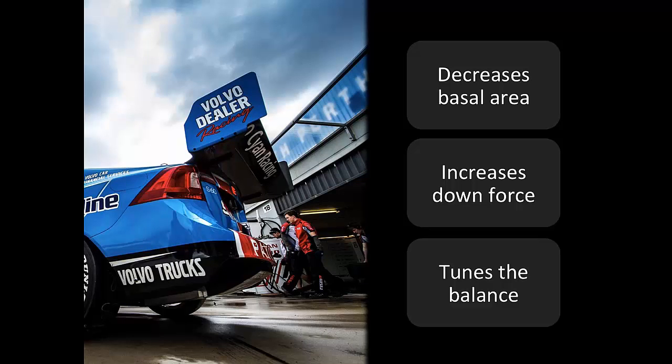So the diffuser can help with increasing downforce, basically by acting as a venturi for helping the exiting flow on the car. One thing you'll see when we developed the Volvo, I did want to put strakes and things on there to increase its efficiency, but I was told it was basically painting a target on the car, because we do get quite violent out there, so you don't want people black flagging you through the race.